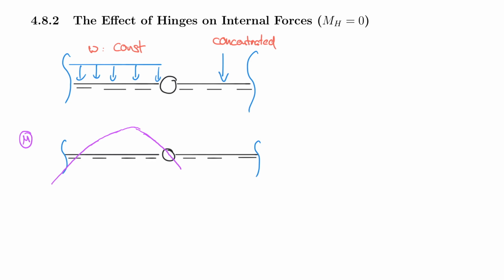And then, because on the right side of the hinge now, the shear force would be a constant, the moment diagram must be linear. And technically the slope at the hinge continues, right? So the slope in this point from the left to the right is pretty much the extension of this line, or the line is the tangent, and then due to that force there, either it goes back up depending on what happens on the right, or it continues to go down. But that's not the point here right now.